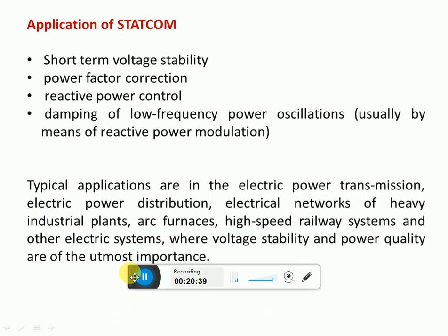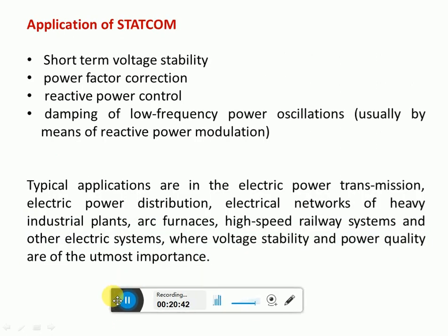The STATCOM is designed in such a way that its response becomes fast and convenient for maintaining the voltage during any fault conditions. So the STATCOM improves short-term voltage stability problems, as it can draw leading current as well as lagging current.